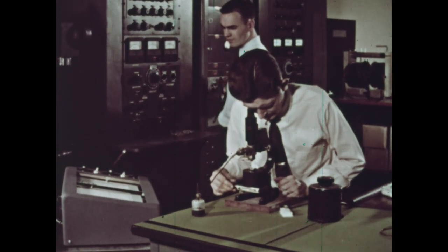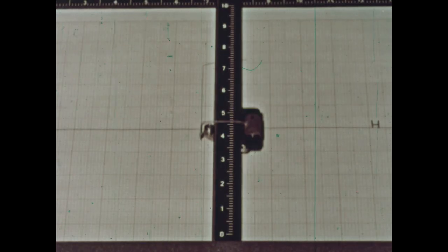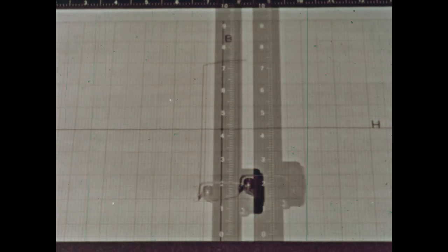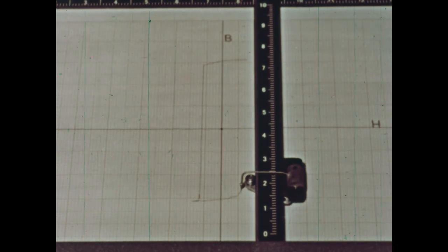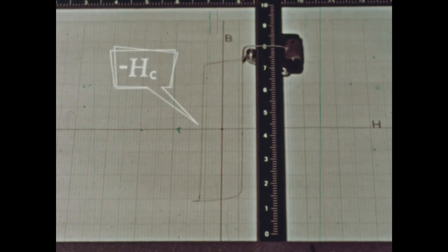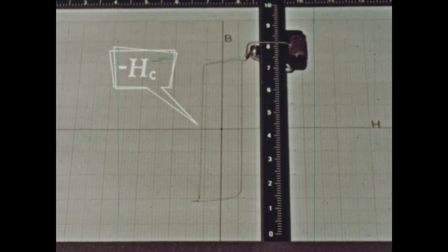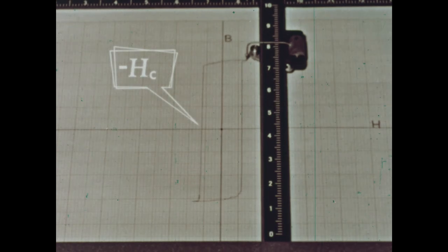In this film, we will discuss the theories that are fundamental to our understanding of hysteresis loops like this one, and show some of the experimental evidence which supports current theories. For example, we will discuss the coercive force Hc, which is the field required to reduce the induction to zero, and the saturation field, which is that field needed to make a sample essentially one large domain.